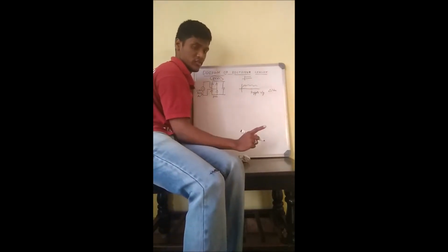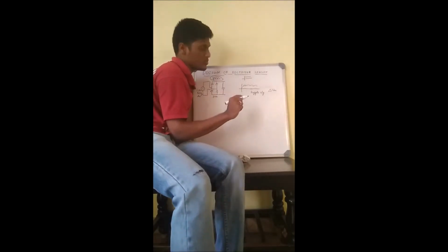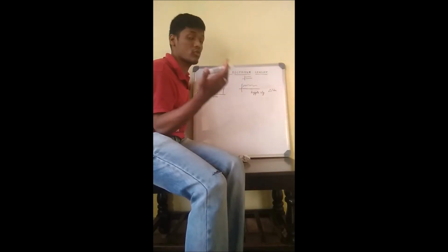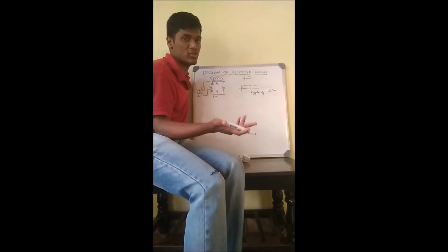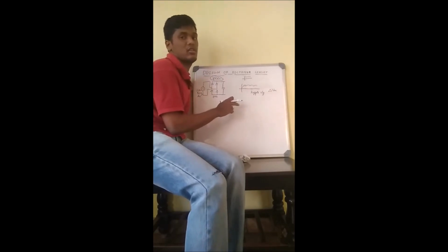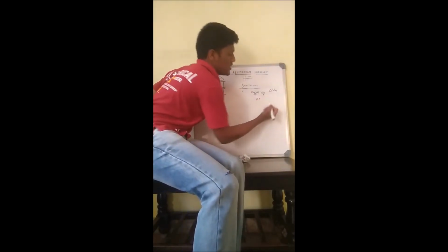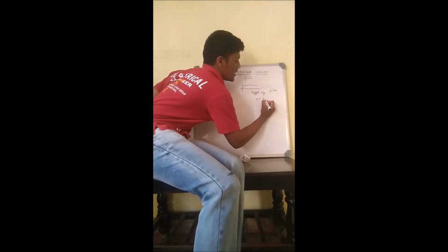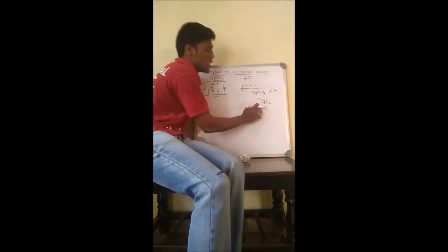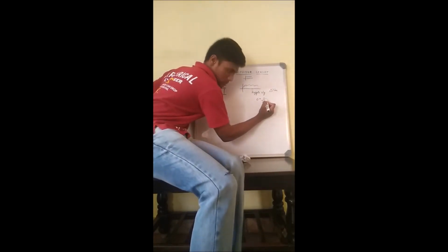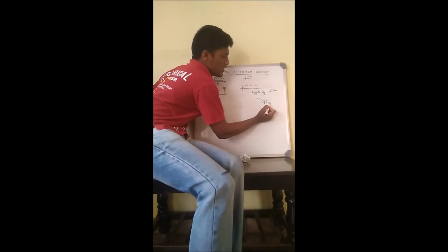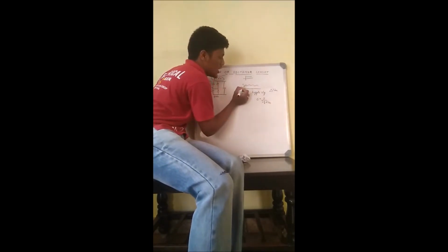So for calculation of the capacitor, we generally assume the ripple voltage to be very small, maybe in terms of millivolts. Of course, it's better to use millivolts. So let me explain how to choose the value of the capacitor. For choosing the value of the capacitor, we have the equation C = I / (2 F delta VR). I is the load current, F is the supply frequency, which is 50 Hz, and delta VR, as I said, is the ripple voltage.